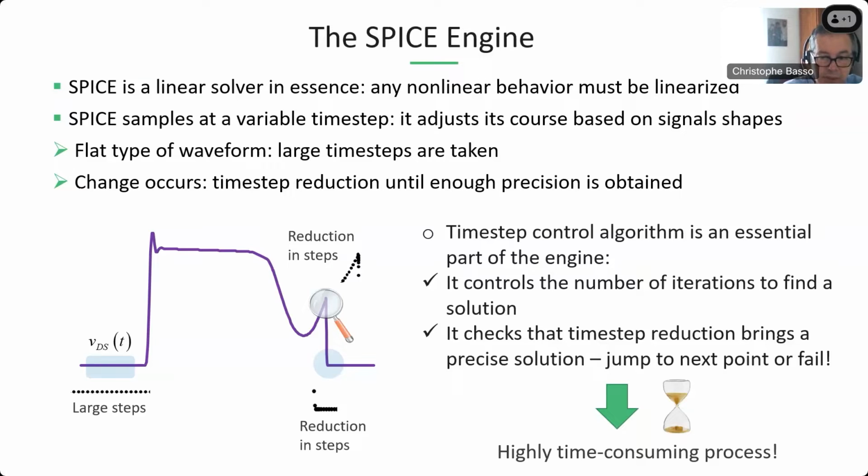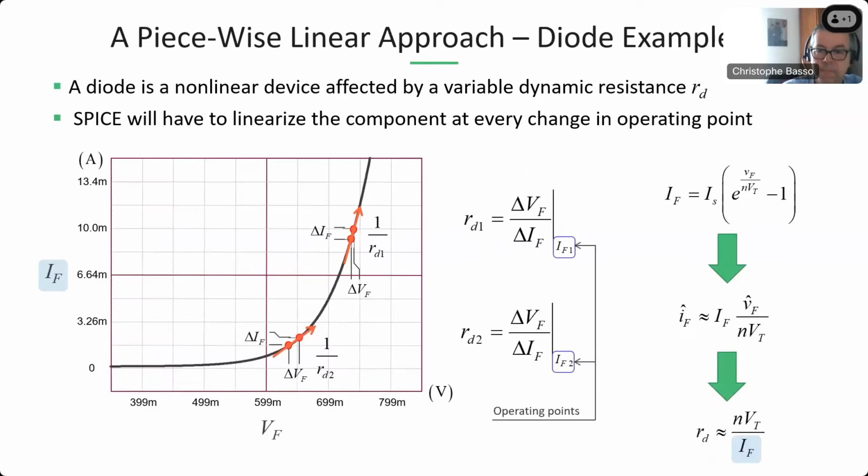Sometimes the step prediction goes down to a very small value to gain in granularity, but it can hit a minimum value and the engine fails to solve the system of equations. And you have a classical frustrating message: time step too small.